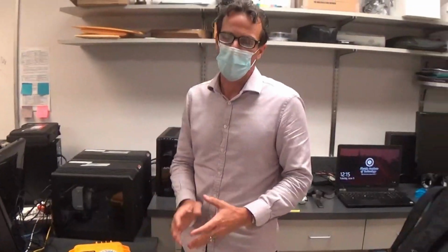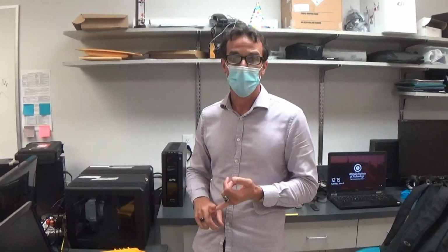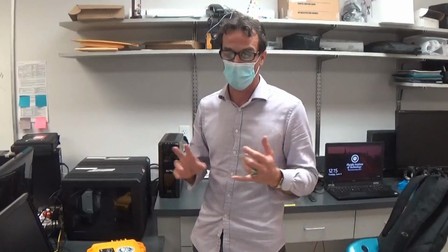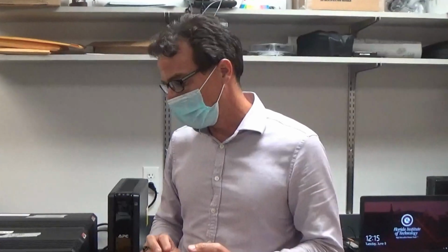So some other very important water properties that as engineers we need to be monitoring are conductivity, which gives us the salinity of the water, temperature, and depth. Both the conductivity, temperature, and to some degree also the depth will allow us to understand what the density of the water is, and that's critical when we're doing acoustic measurements like using ADCPs, because the sound from the